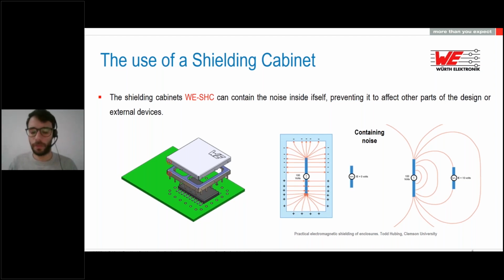This could be, for example, that we have in our design an RF stage, and close to it we have the power stages, or different design stages that are close together, because now electronics are also getting more concentrated and in smaller housings. So we need to keep these stages separate, because if not, we'll have the problem of them affecting each other.